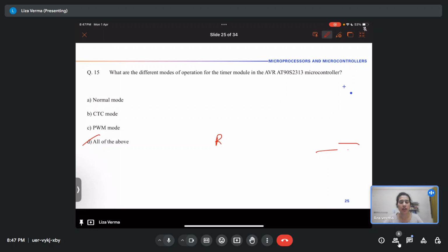If there was a borrow, then the carry flag is 0, and if there was no borrow, the carry flag is set, right? So for these instructions where subtract is done with the carry, the complement of carry has to be used. This is done internally, so you don't have to worry about it. Just something nice to know.